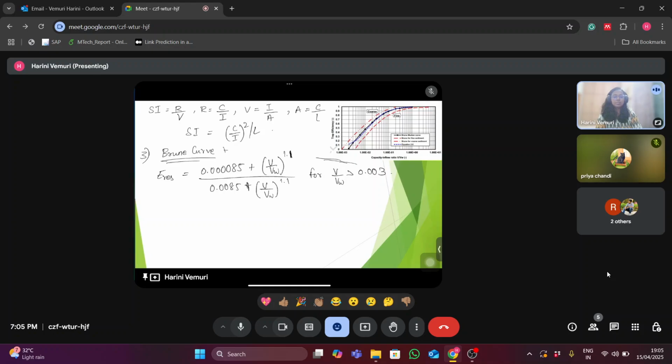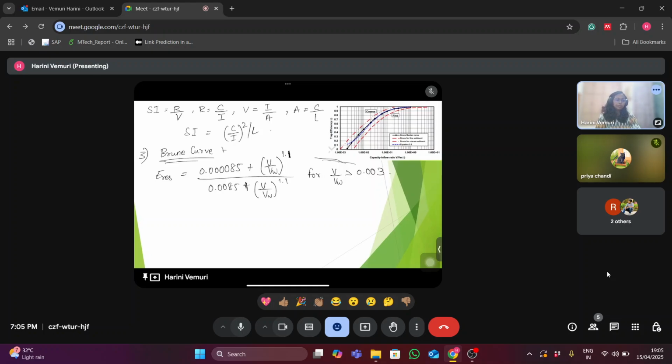The VW is the average annual inflow volume and V is the storage volume of the reservoir below the line through bed level and upstream pump. So here we have only two parameters, V and VW, so it is most widely used. But the problem is that it is established using only normal ponded reservoirs, so it might not be applicable for all kinds of reservoirs.